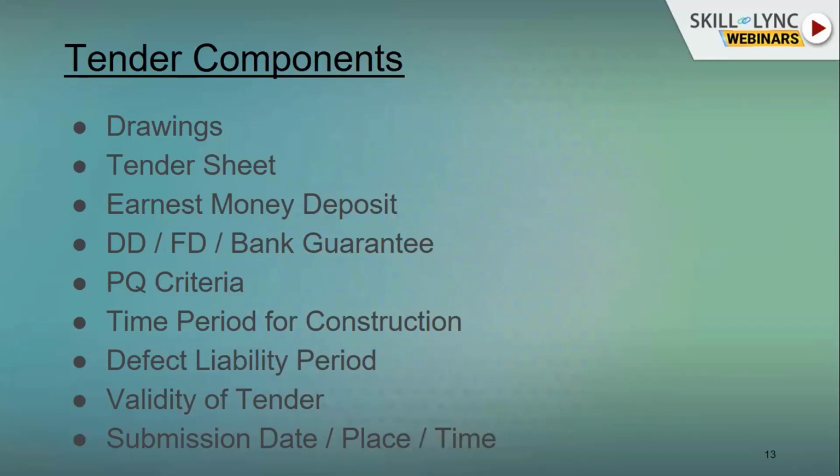Security deposit is nothing but the deposit given by the contractor to the employer to carry out work, and the employer will deduct a security amount in the running bill of the contractor, so that there is a security amount with the employer, so that the contractor will work on the said terms with the said rates.